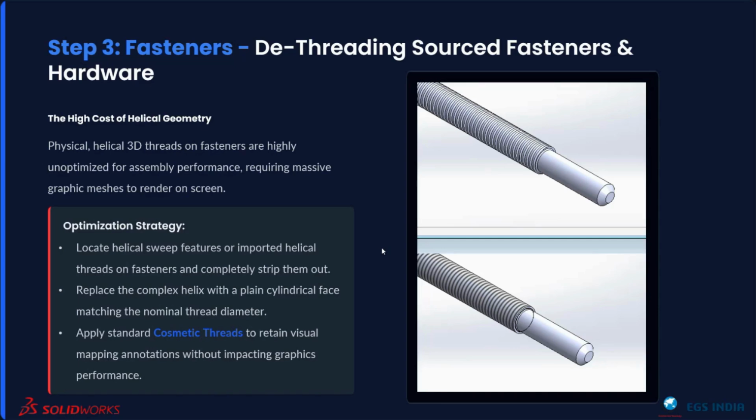We are just going to denote that with a callout in your drawing sheet. So why have it in your top level assembly over here? In this case, you can see that there's not much difference between the top component and the lower component visually, because what I've done over here is used a concept called cosmetic threads. What cosmetic threads do is add a small appearance on top of your component to show that there is a thread present on it.